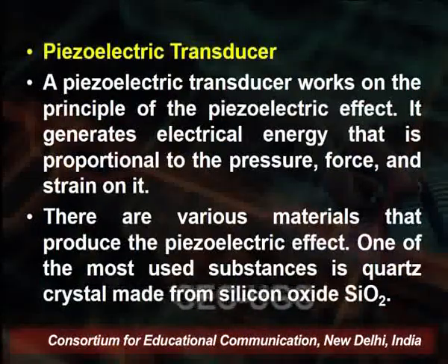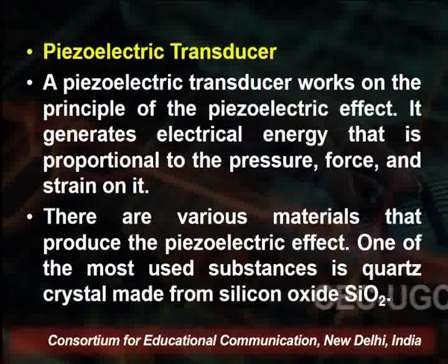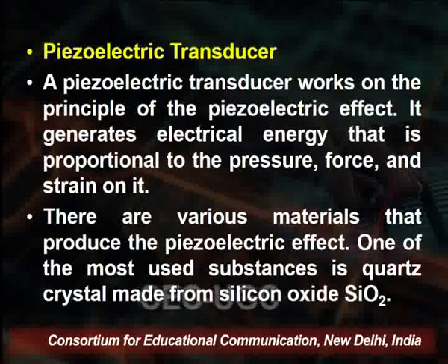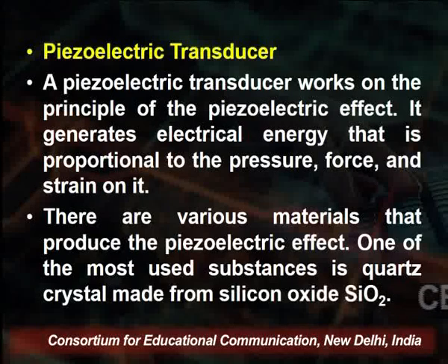Next are the piezoelectric transducers, which are used to convert pressure, force or strain into an electrical signal. A piezoelectric transducer works on the principle of the piezoelectric effect, and it generates electrical energy that is proportional to the pressure, force and strain applied on it. There are various types of materials that produce the piezoelectric effect, and one of the best examples is the quartz crystal made from silicon oxide.